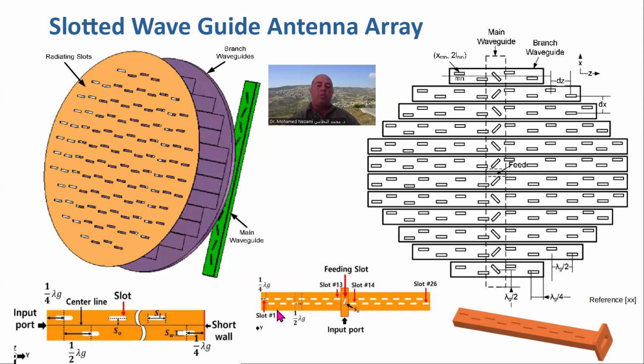So just to show you, this is a schematic showing basically how symbolically a single section of this is designed. We have the input waveguide in here, we have a slot, a feeding slot inclined, okay? And then we have the regular slots in the stacked waveguide on top, and these follow the same rules that I just mentioned: quarter wavelength from each shorted end, and then a half wavelength spacing between each other.